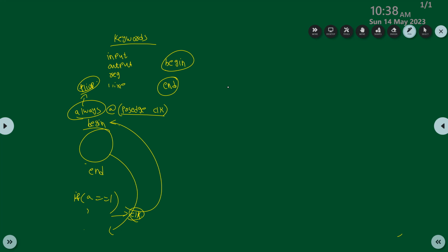Yes, W1 will be X up to 4 nanoseconds. X in the sense, in the silicon it is not throwing X. It might throw 0 or it might throw 1. That we cannot guarantee and we need not consider. You cannot predict that value, whether it is 0 or 1, because you are not applying any valid input. So whatever value is on W1 is unpredictable.